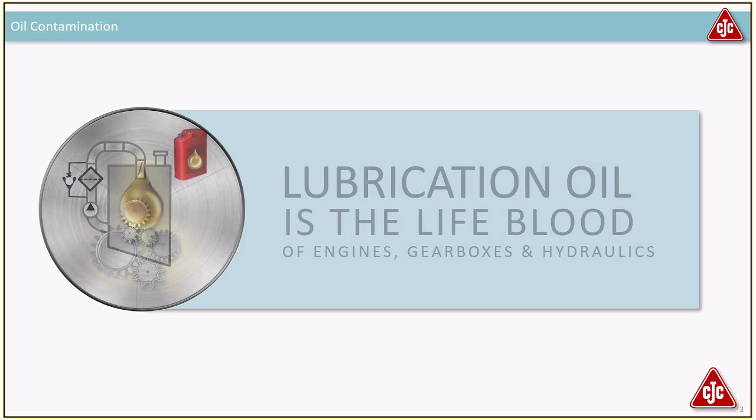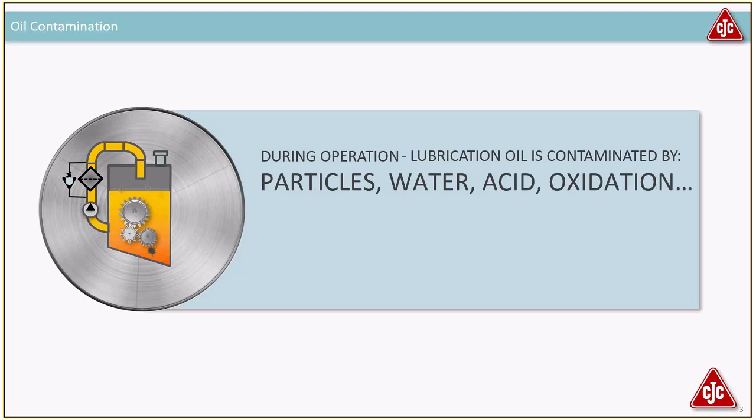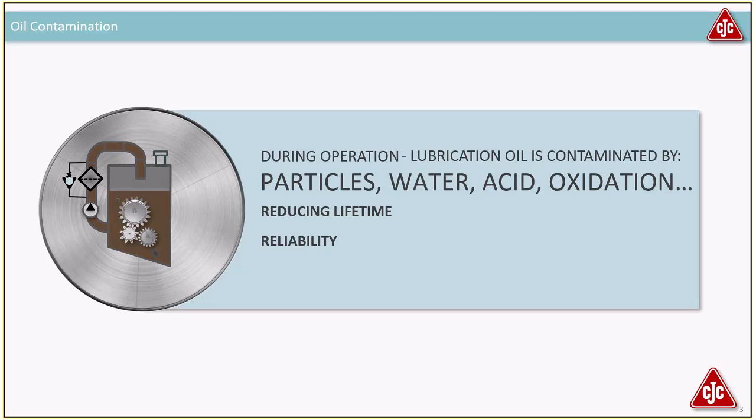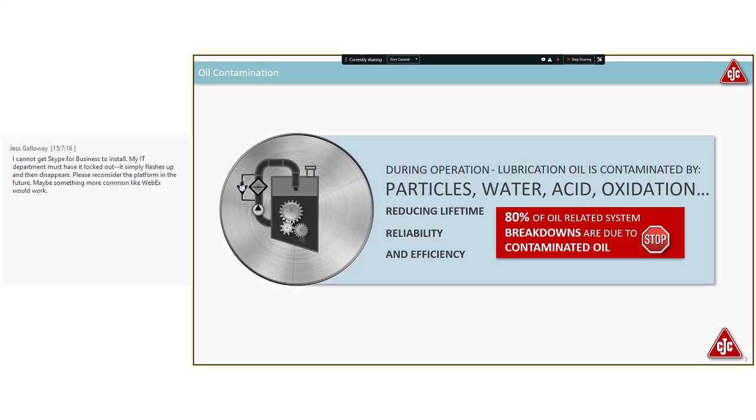So what we want to do is keep it clean, but unfortunately during any operation the lubrication oil will be contaminated with particles, water, acidity and oxidation. It's part of the same thing. That will reduce the lifetime of the machine, and the reliability and the efficiency will be harmed as well. Studies have shown that 80% of oil related breakdowns are actually due to contaminated oil. So there's a huge amount of money in actually cleaning the oil and keeping it cool, clean and dry, as Noria say.